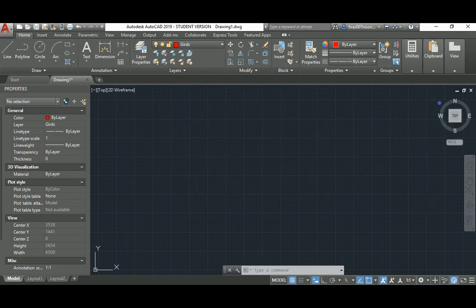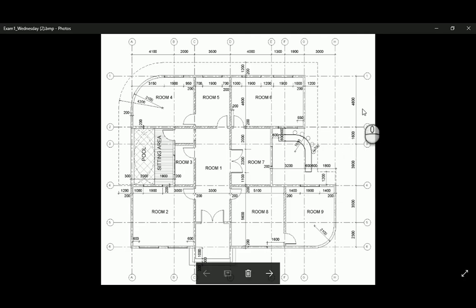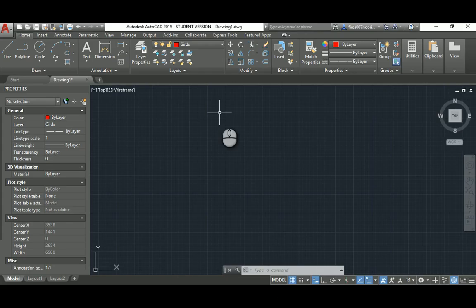Now, a quick look again. That's around, let's say, 5,000, 7,000, 12,000, let's say 16, and then around 20 meters. So if I add 5 here and 5 here to roughly know the distance from this point to this point, it should be 30 meters. So activate the L command, which is the line, and place a point here.